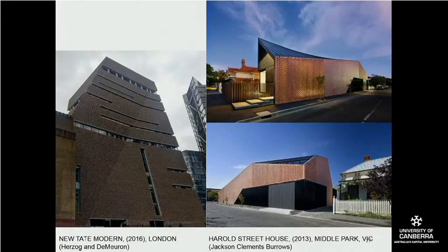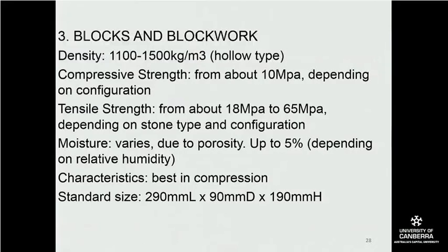So finally, we talk about blocks and block work. As I said before, when we talk about blocks and block work, really we are talking about concrete blocks. And block work, of course, are walls of concrete blocks joined by mortar. The density of concrete blocks is much lighter than bricks or stone, because they can be made to be quite hollow.